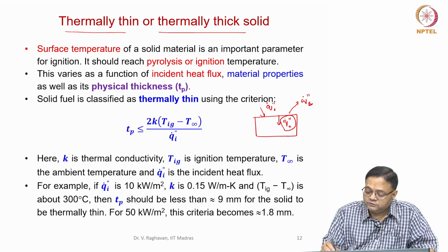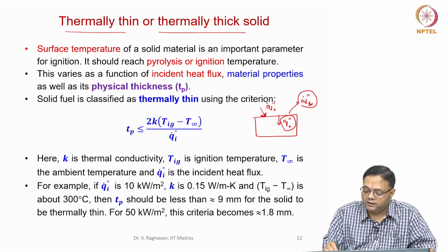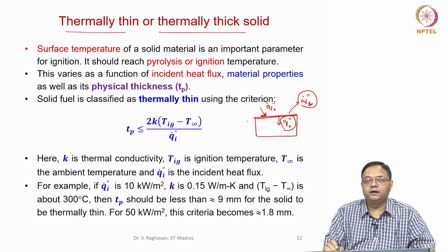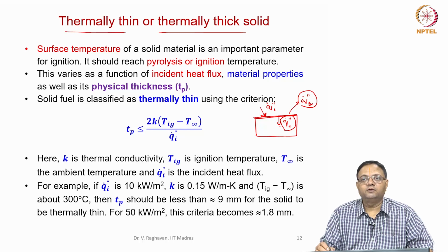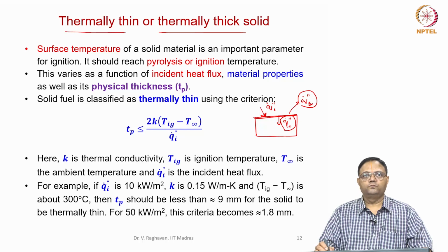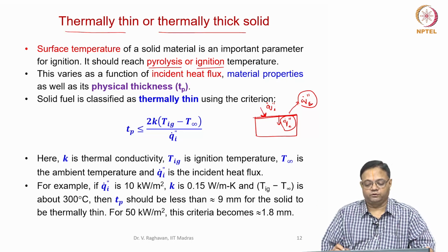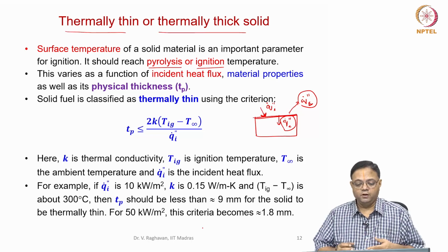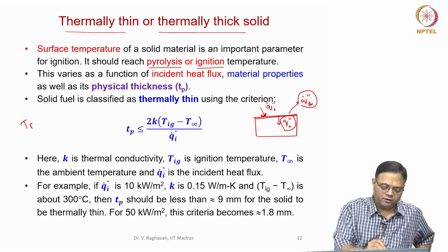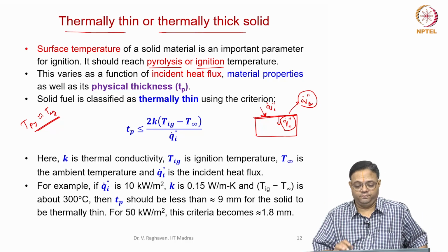we will see that the surface temperature rise depends upon the incident heat flux as well as the conduction which is happening within the solid. And surface temperature actually dictates the pyrolysis process or the ignition process, because we have to reach the pyrolysis temperature, which is also called ignition temperature. Pyrolysis temperature and ignition temperature, T pyrolysis is the same as T ignition, where a sustained flame is seen.